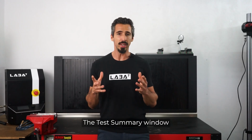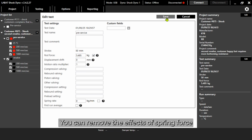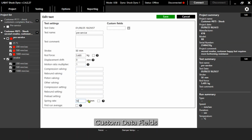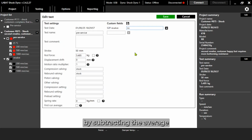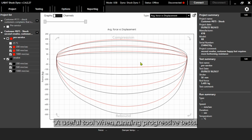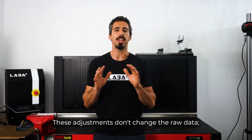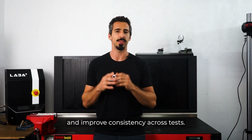The test summary window offers additional tools to refine your data. You can remove the effects of spring force by entering a known spring rate, create and apply custom data fields for tracking things like serial number, build specs, or tuning notes, and normalize all runs by subtracting the average of the first test interval, a useful tool when running progressive tests. These adjustments don't change the raw data. They help clarify the graphs and improve consistency across tests.